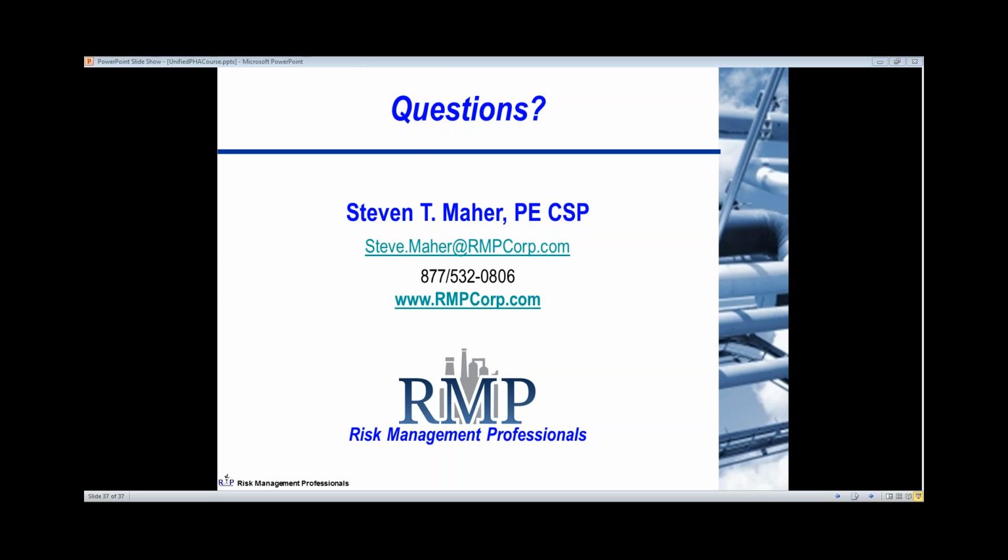And if you're taking a BPCS safeguard credit when you've got a BPCS failure that's your initiating event, you have to be careful. If you're taking more than 1 BPCS credit in your safeguards as independent protection layers, you want to make sure they're truly independent, and your instrumentation person can identify that.